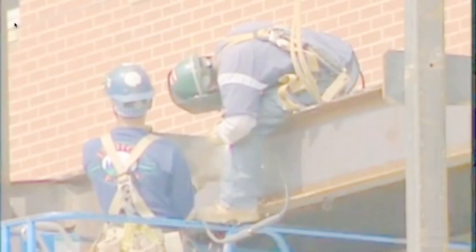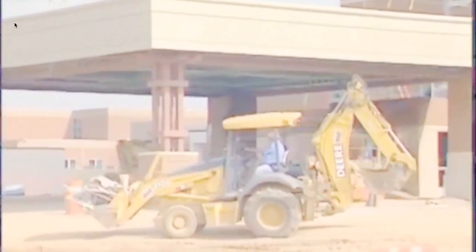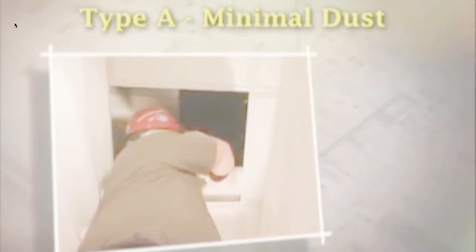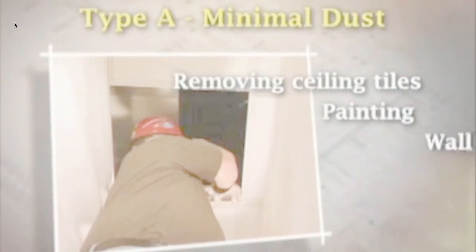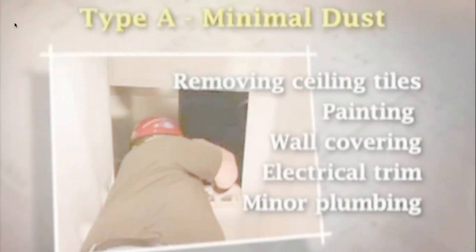In order to identify the containment measures needed for a project, Step 1 of the ICRA defines the type of construction project in terms of how much dust and dirt are likely to be generated. Type A or minimal dust projects include inspections and non-invasive activities, such as removing ceiling tiles for inspection, painting with no sanding, wall covering, electrical trim work, and minor plumbing repair projects.